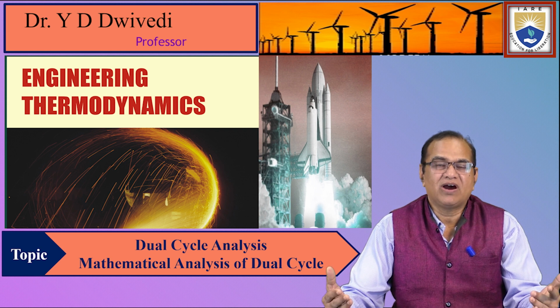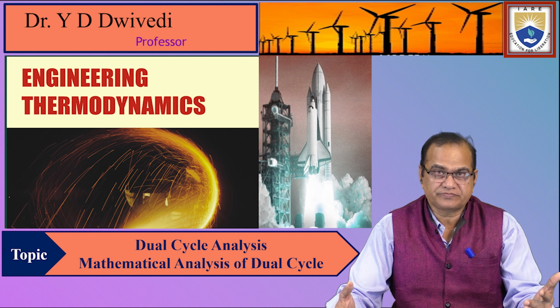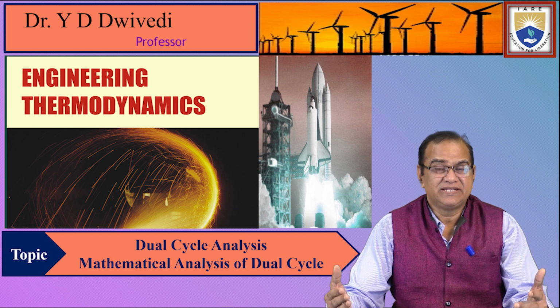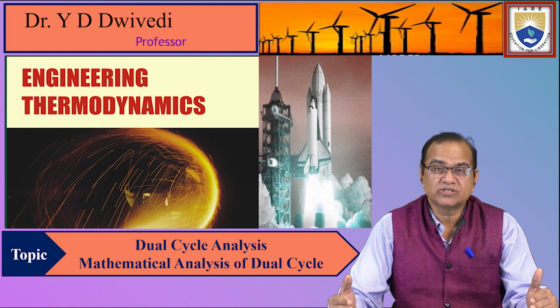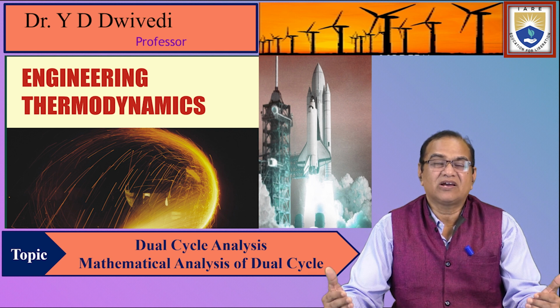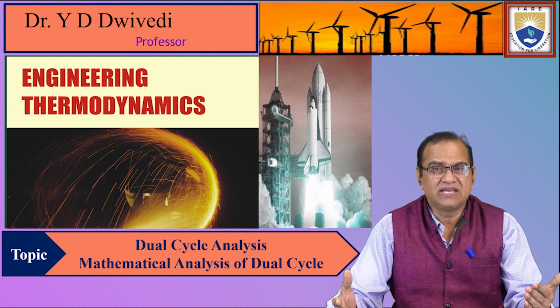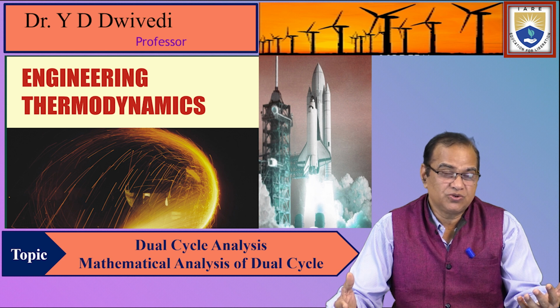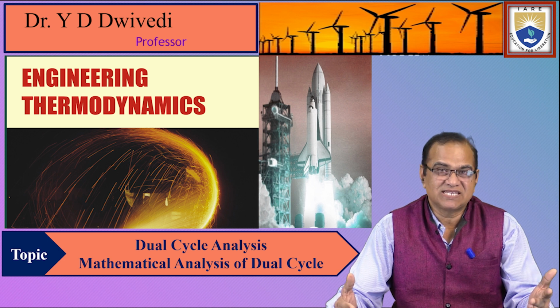In the same way, we have already done the diesel cycle. In the diesel cycle, the ignition is taking place at a constant pressure process. However, in the Otto cycle, the ignition or the heat addition is taking place at a constant volume process. So this is the only basic difference. For the given compression ratio, the efficiency of the Otto cycle is better than the efficiency of the diesel cycle.